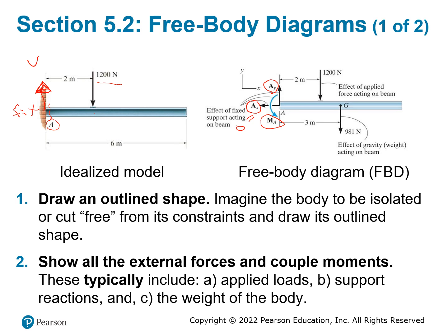If you consider the weight of the beam, then we can also put the weight of the beam into the problem like this and here. So if they give you the weight, which is 981 here, you're going to put the weight at the center of the beam. If this is uniform, it's just going to be in the middle of the beam.